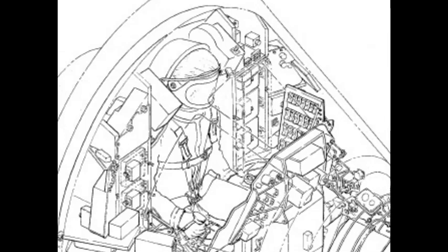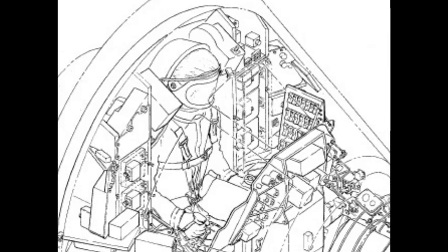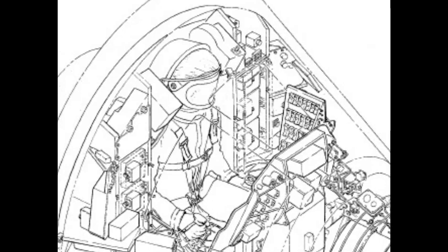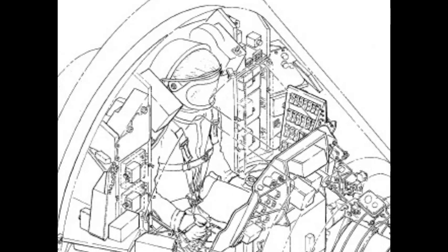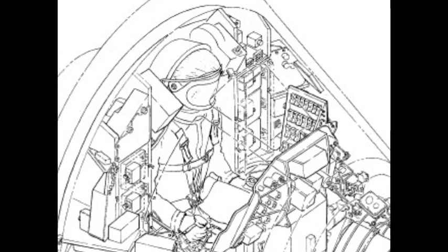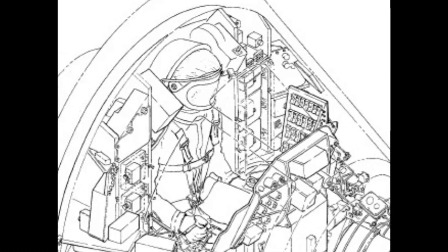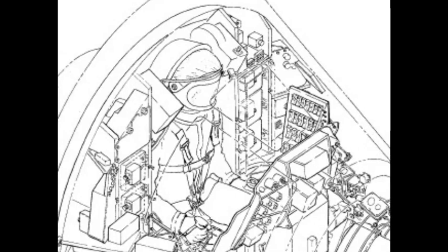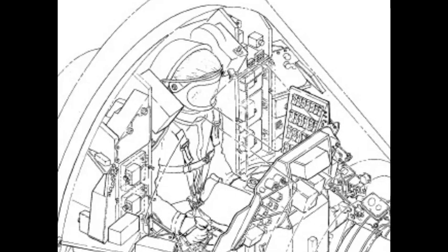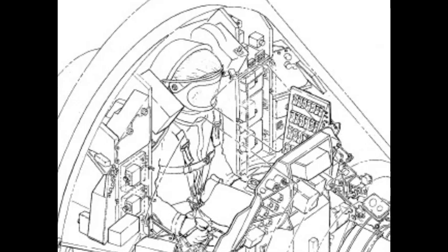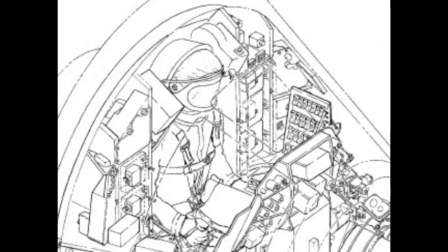During capsule launching phase, and up to the capsule tower separation, the spring-loaded destabilizer flap is held flat against the antenna fairing by means of a quick-release pin attached to the escape tower. Jettisoning of the escape tower releases the flap, which is spring-loaded to the outboard position. When the capsule descends to 10,000 feet altitude, the antenna fairing is automatically jettisoned from the capsule by the firing of the fairing mortar gun.